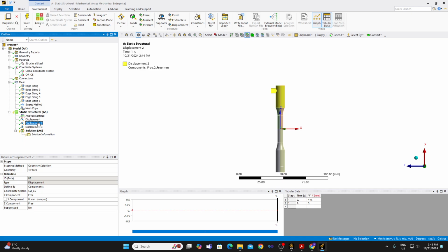Also it is preventing the motion, since it is on the entire surface. It is also preventing the rotation. So it's a constraint in the theta direction, so it is also preventing the rotation about the z-axis. All the 6 constraints are literally over here on the top surface. You have given all the constraints.